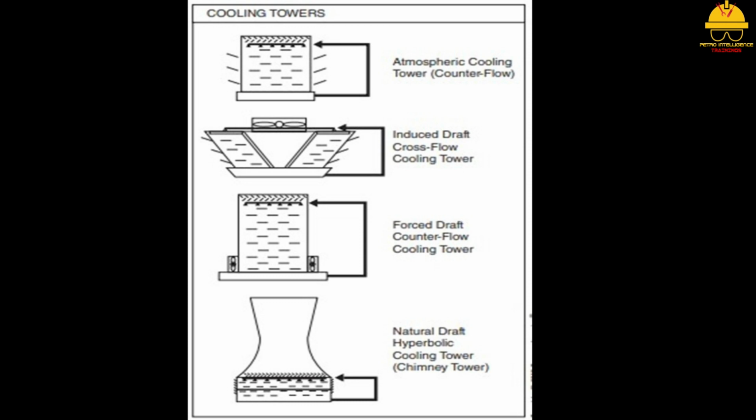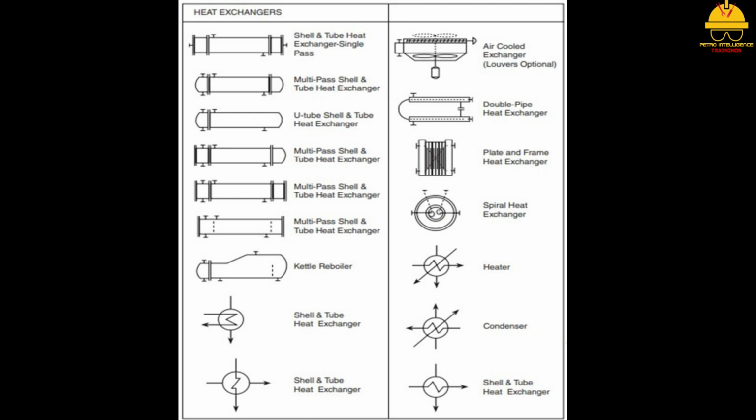The symbol for a heat exchanger clearly illustrates the flows through the device. It is important for a process technician to be able to recognize the shell inlet and outlet and the tube inlet and outlet flow paths. A heat exchanger with an arrow drawn through the body illustrates whether the tube side flow is used to heat or cool the shell side fluid. The downward direction indicates heating, while the upward direction illustrates cooling.